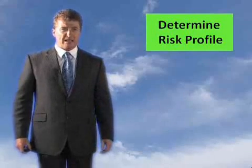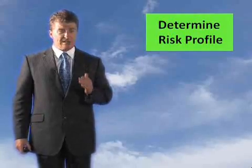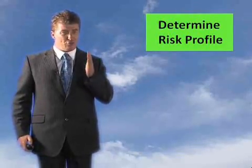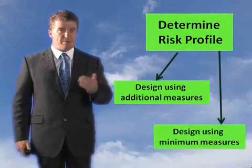How do you use BS9999? Well, I'm going to go through the process with you now. The first thing you need to do is determine the risk profile. So you get that from the tables or you create it. If it's an A1 and A2, you need to get your risk profile. Then you can either use additional measures or you can design using the minimum measures.